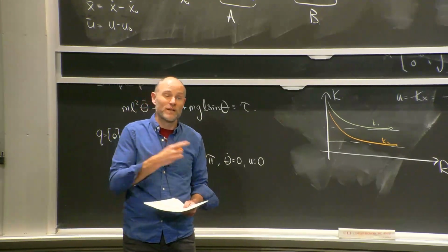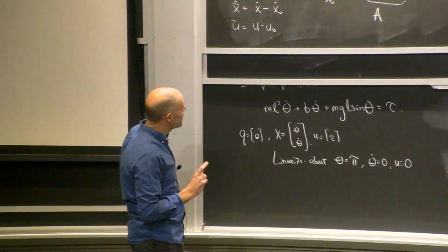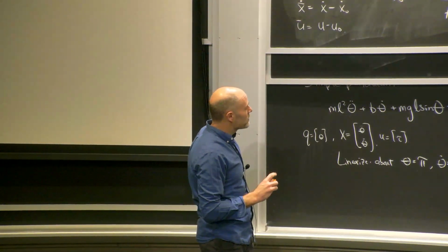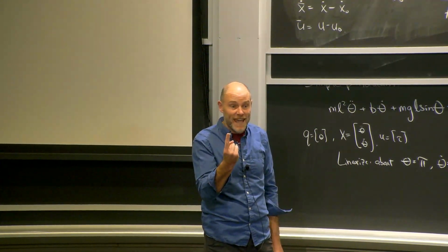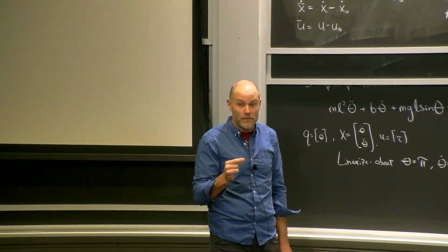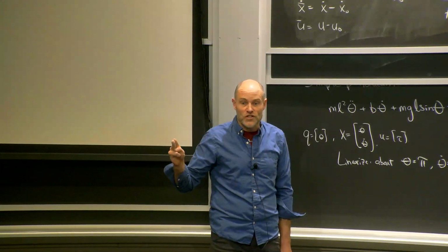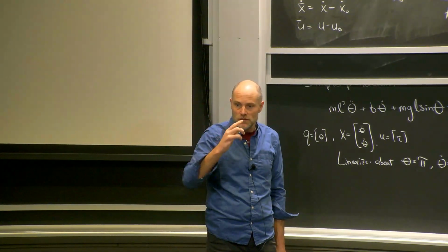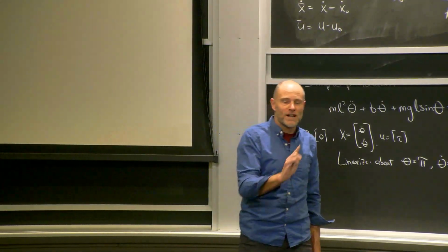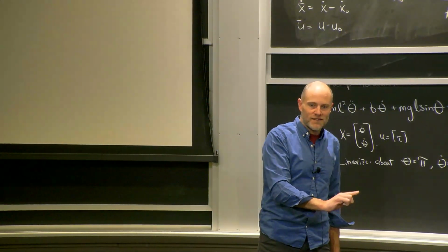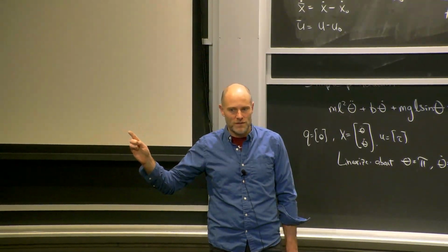There's actually even a better way to parameterize. So, we talked about two different parameterizations of the controller. You could parameterize K directly. The space is a little complicated. Or you can parameterize Q and R. This parameterization is easy. Just pick something positive, and you always get a stabilizing controller. But there are stabilizing controllers that exist which cannot be gotten from LQR by changing Q and R. Right?